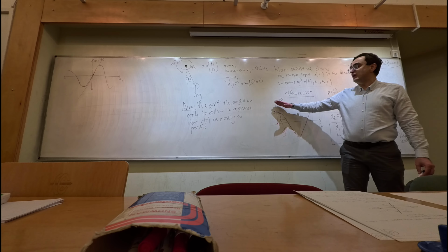Our design procedure tells us that we need to take the derivatives of the output until the input appears. The smallest order of derivative where the input appears on the right-hand side is called the relative degree of the system. In this case, the input appeared on the right-hand side when we take the second-order derivative. So we call the relative degree of the system 2. That is the minimum order of derivatives before the input signal appears on the right-hand side, and here that derivative order is 2.